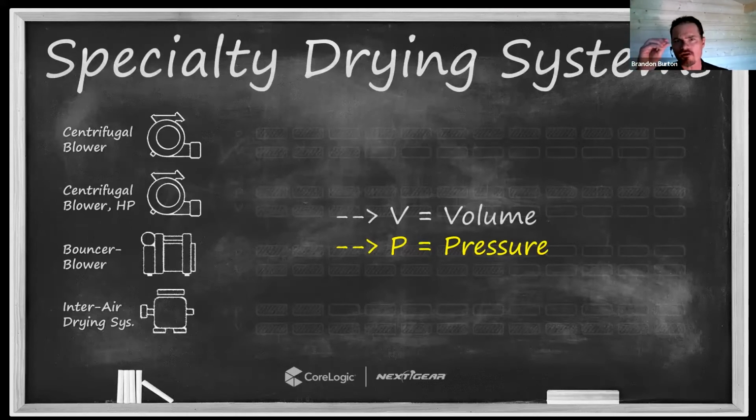We're talking about very, very small spaces. So if I can get an air exchange through there once every minute, that air is actually moving pretty quickly underneath that floor. So I don't need a tremendous amount of volume to make that happen, but we need some, right? And generally speaking, the more volume I move through the space, the more rate of exchange and the better the velocity, right? So higher volume is definitely better, right?